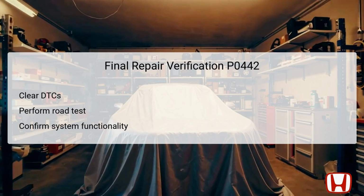Pay attention to the functionality of the EVAP system during different driving conditions as part of the verification process. Ensuring everything is operating as intended is essential to validate that the issue has been resolved and to prevent the recurrence of the P0442 code.